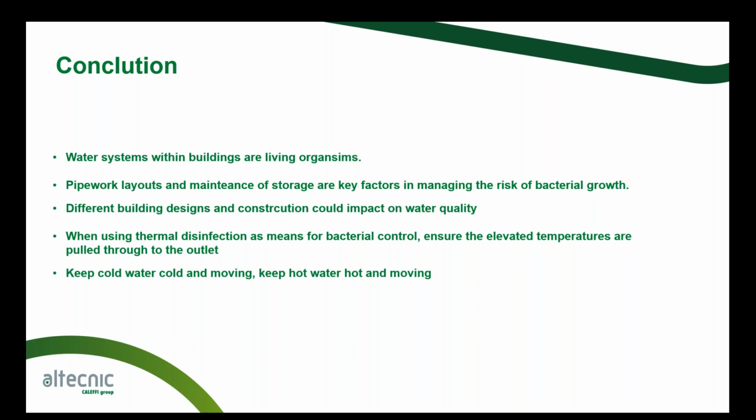When using thermal disinfection as a means for bacterial control, ensure the elevated temperatures are pulled through to the outlet. And remember, a very simple way to remember this is: keep cold water cold and keep it moving, and keep the hot water hot and keep it moving. Now, we want to be able to remove all those areas of risk when it comes to bacterial growth. And that is me done.